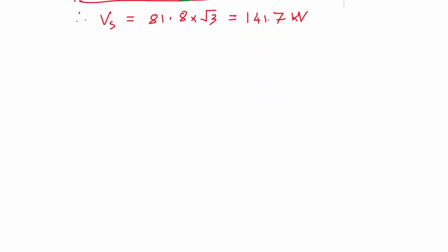Now what is percentage regulation? Percentage regulation is equal to VNL minus VFL by VFL into 100%.